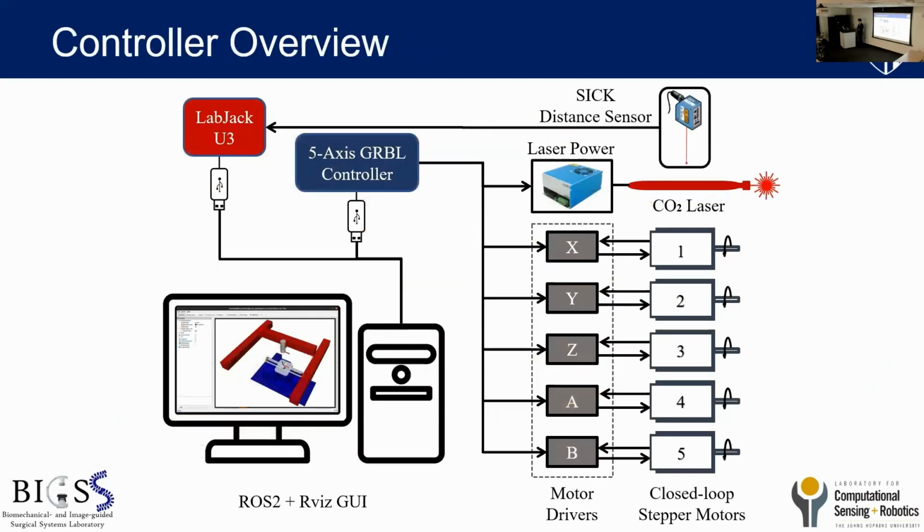And this is the controller overview. There are 5 closed-loop stepper motors, and the laser is controlled by the Grbl controller. And then I developed a ROS interface to communicate with the controller and the distance sensor.